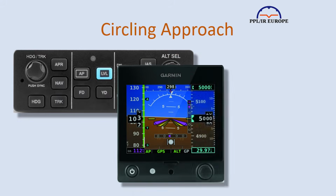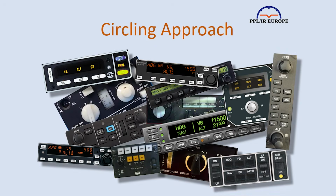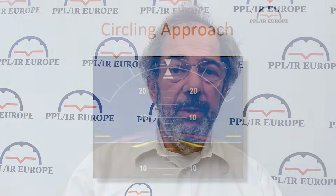A brief word about automation. You have the choice of using autopilot, flight director or raw data, and each has pros and cons. Most of our autopilots are restricted from use below 800 or 1,000 feet unless on a coupled approach, which does not include a circling approach. I'm sure someone will correct me in the comments, but I can't think of one GA autopilot which is permitted to be used any lower, and most circling approaches will be lower than that, so they're out of the equation.